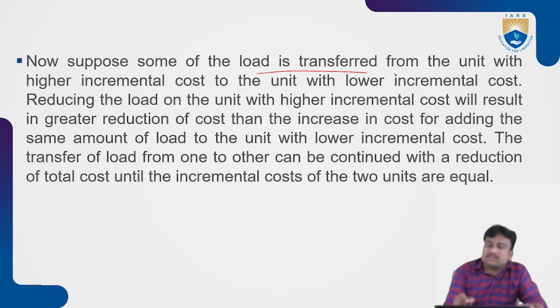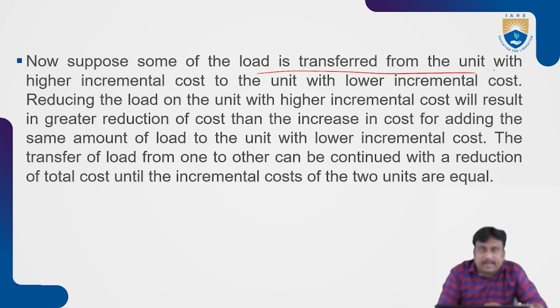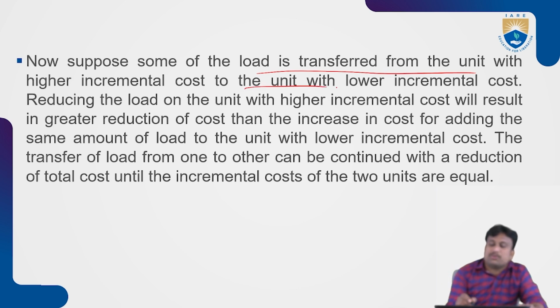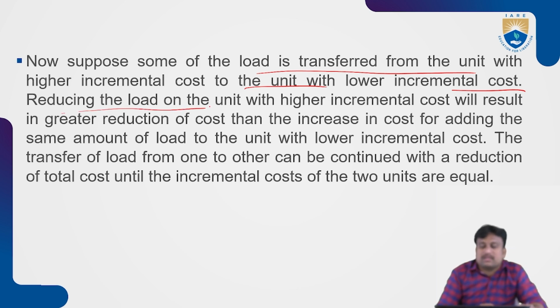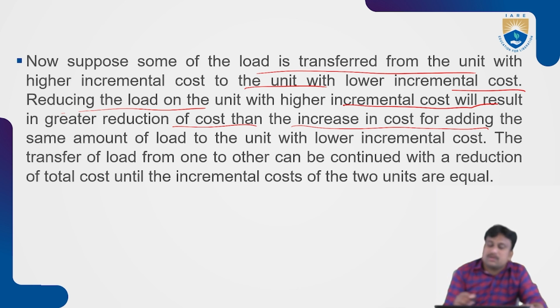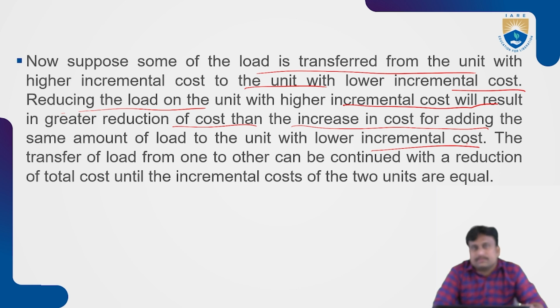Some of the load is transferred from the unit with higher incremental cost to the unit with lower incremental cost. Reducing the load on the unit with higher incremental cost will result in a greater reduction of cost than the increase in cost of adding the same amount of load to the unit with lower incremental cost.